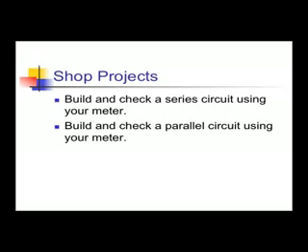To troubleshoot, there are some basic rules. Start at source and work your way from there. There's no reason that if you don't have source you should even go any further. You need to stop and find out why. If you get any voltage across a switch, that switch is open or bad. If you get voltage at a load and the load is not working and has failed, replace it.